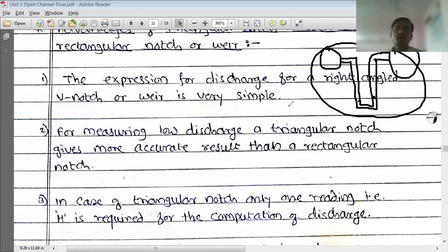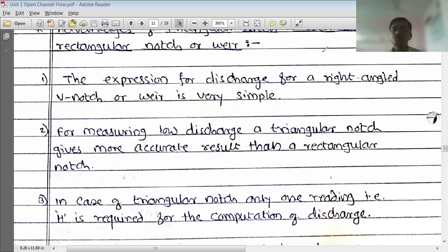In contrast, the inverted tube manometer contains oil which has a specific gravity less than 1, and for a small fluctuation in pressure, you will observe more deflection in the manometric reading, right? That is why we concluded that inverted tube manometers give more accurate readings for smaller pressure differences.